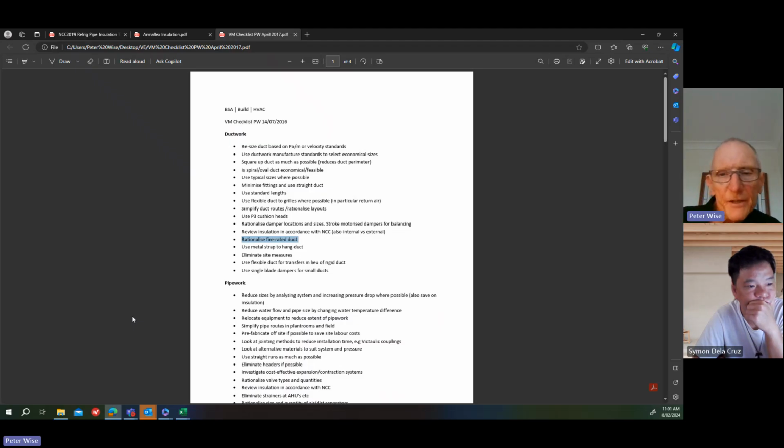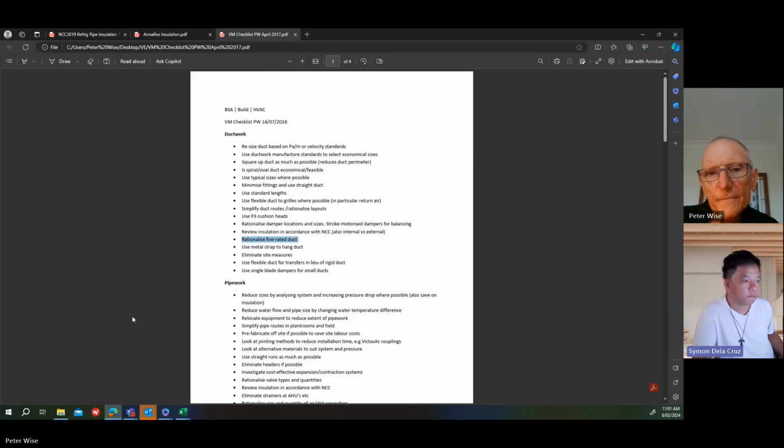So we had to get supply air into those compartments and then exhaust out. When you have to keep supplying air in fire mode, but it's passing through a separate fire compartment, then that duct has to be fire rated, because you want it to keep running in a fire mode.